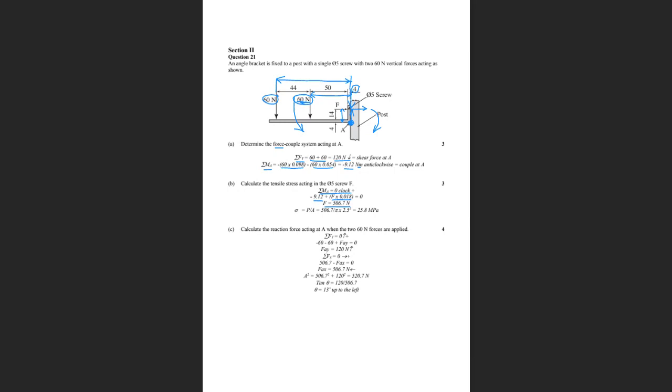Then stress. Now I haven't put where here because I did this mainly for teachers for the solutions in the independent final year 11 exam. And so stress equals load over area. Put your formula. So you've got the force divided by the cross-sectional area. I haven't put 10 to the minus 6 in because I'm going to call it megapascals.